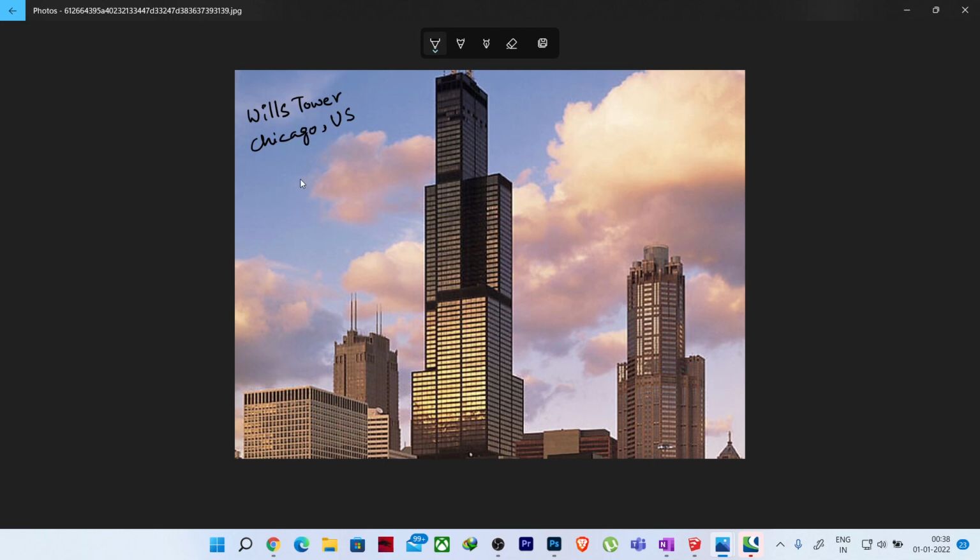So this is the structure, Willis Tower, Chicago, in United States. This is the example of our bundled tube system. And if you want to see a structure with core wall, most of the tall buildings are having core walls. There are a few with belt truss, and this one also, which I have called outrigger.